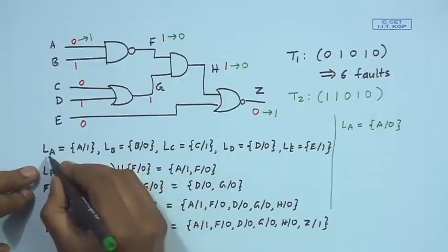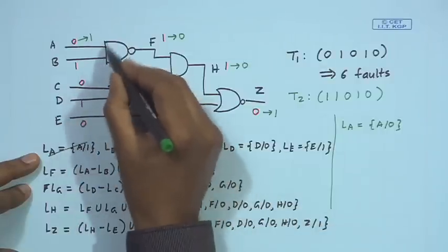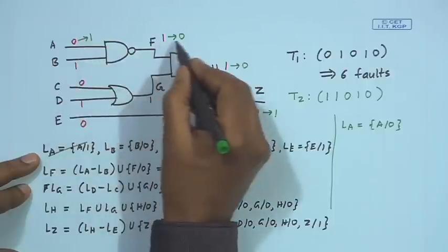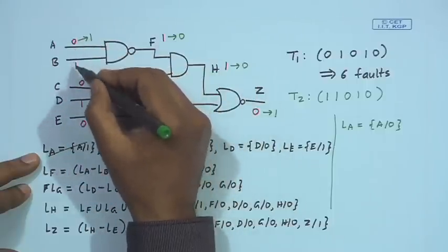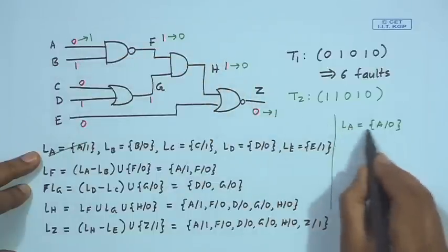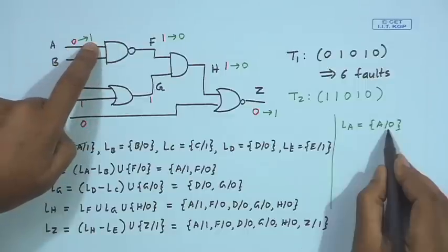This has changed. So, the old list gets removed. Now, this NAND gate is having 1 1 as input. So, the condition for the output changing will be LA union LB. So, LF is recomputed, there has been a list event. List event LA has been modified, also there is a logic event, the input has changed state.